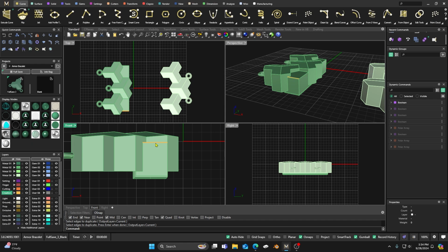Now, like I said, we need some thickness here. So I'm going to grab that curve, I'm going to click on my thing, and I'm going to drop it down to negative 0.6. All right. Now, this curve here, I'm just going to go right back and grab that dupe edge. I'm going to grab that one, hit enter, and I'm going to offset it a negative 0.6. Okay, so it's starting to get me a box there, right?